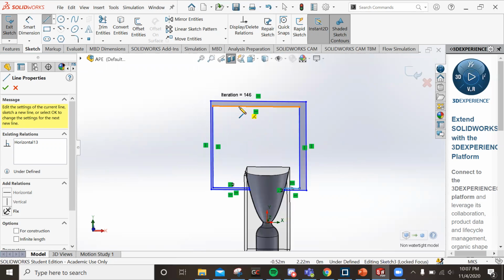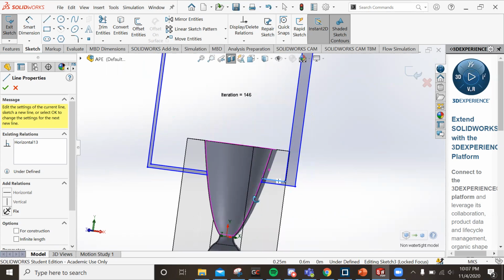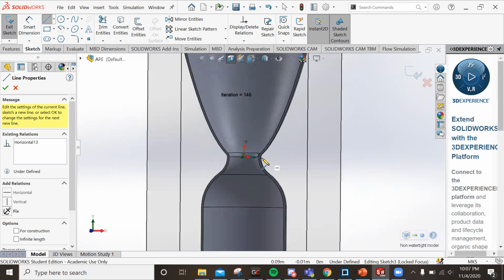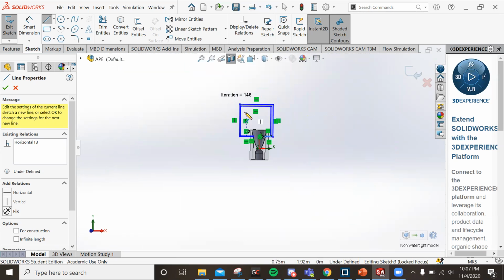And then you can put the boundary condition on this wall instead of the end of the nozzle. And then you can see whether you're overexpanding if the exhaust gases go out and then go in. You can see if you're underexpanding if they go out and continue to bell out, or if you perfectly expanded it and they just go off in a straight line. You'll be able to see that. So yeah, I think that's about it for SolidWorks FlowSim. I'm just gonna end this video here, I guess.